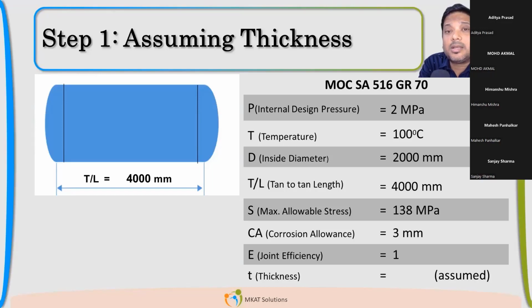External pressure will not happen when the vessel is in operating condition. The pressure vessel will not experience external pressure then. Is it making sense? It will happen when there is an offset condition.